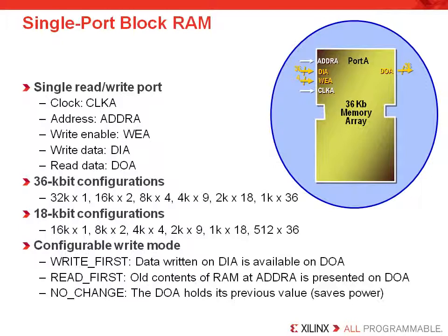Since the block RAM can be segmented into 36K or 18K bit sizes, you're allowed to build with the widest implementation of 72 bits on a single block RAM. This may require you to configure the block RAM as dual port and then use the two output buses as one 72-bit bus. If you had segmented your memory into two 18 kilobit blocks, you would be allowed to build at the 36-bit data width. This flexibility enables the user to double the memory bandwidth per block memory if desired.